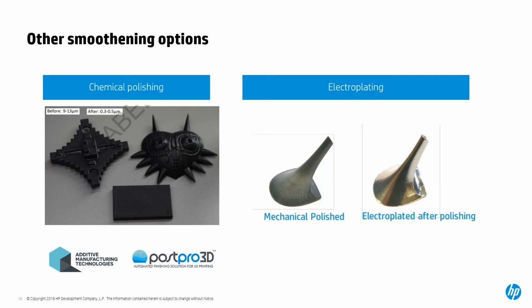Yeah, that's another great question. So when we are dyeing the parts, as we are using nylon 12, you may know that the nylon family is a hygroscopic family. So all of those are hygroscopic materials. Then inside the nylon family, there are different levels. One of the ones that absorbs the most water is nylon 6. But still in nylon 12, we can have a water absorption that, depending on the geometry, can go from 0.5% up to 5, 6, 7%.